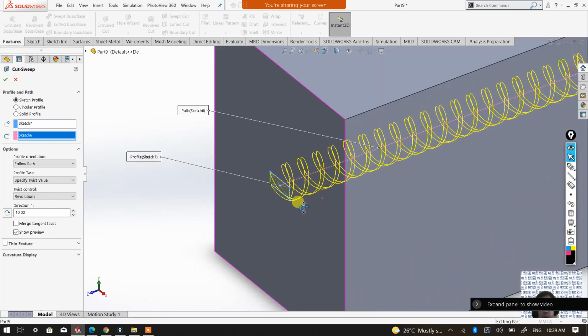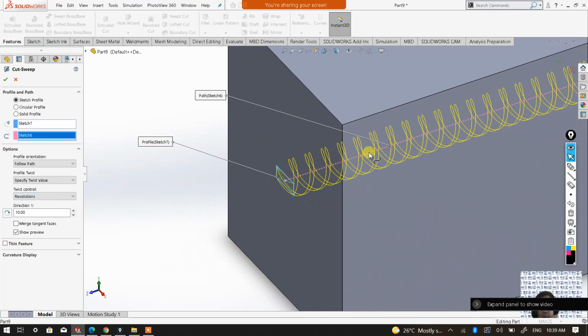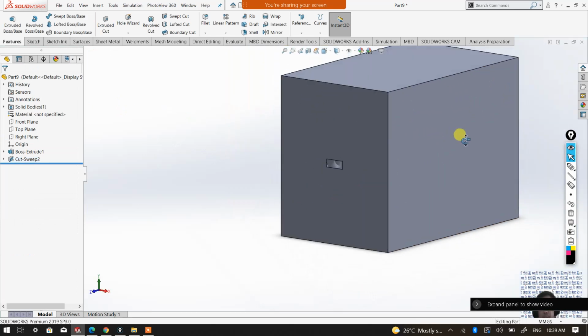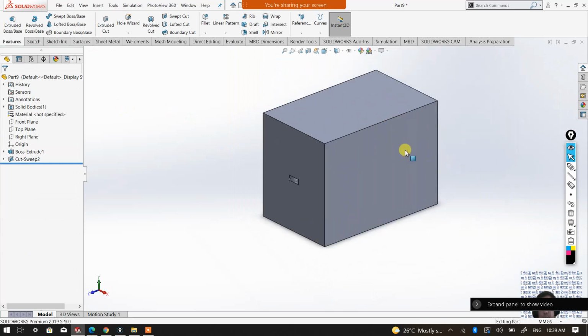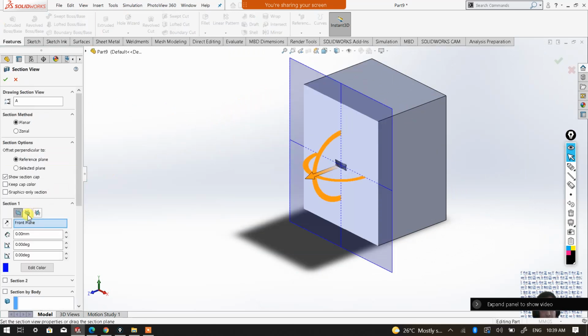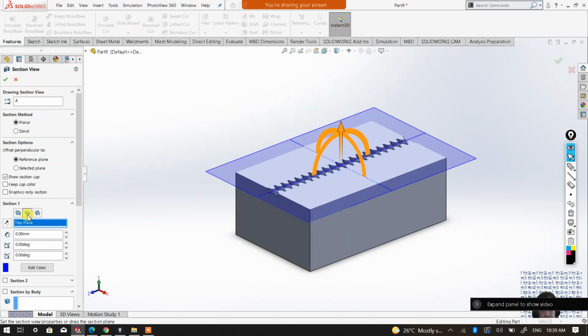Have a look, you can do the analysis. If 100, how does it look, especially those related to the pitch. Okay, pitch which is between from one twist to another twist, or from one revolution to another revolution. Okay, and then click OK. Okay, so there you are. So this one is pretty hard for us to have a look. However, what you can do is go to here, which is section view. Okay, you go to section view here, and you can just simply try out this one. Okay, there you are.